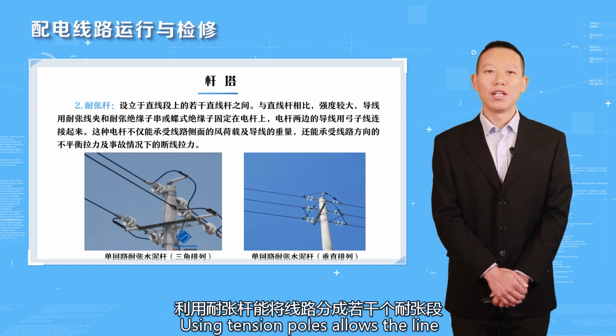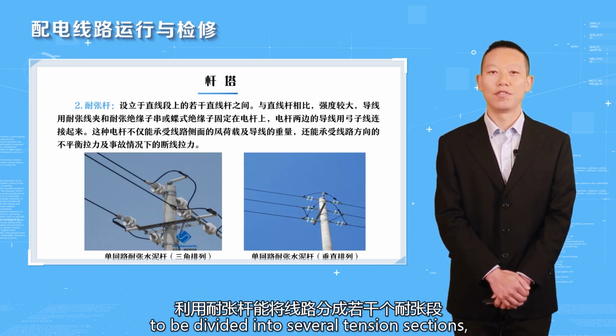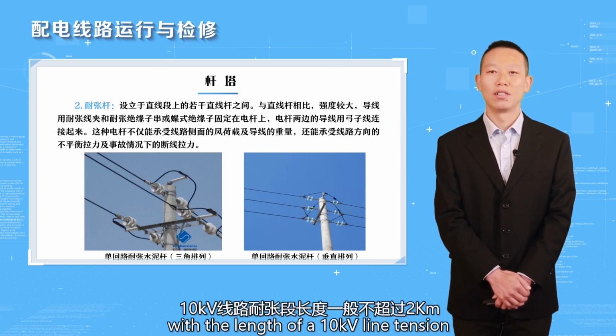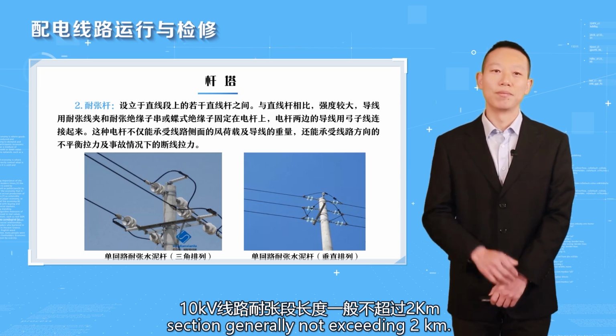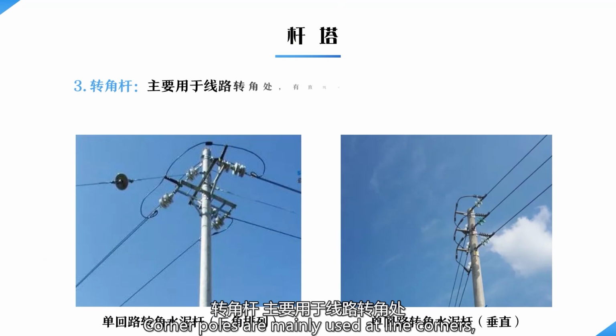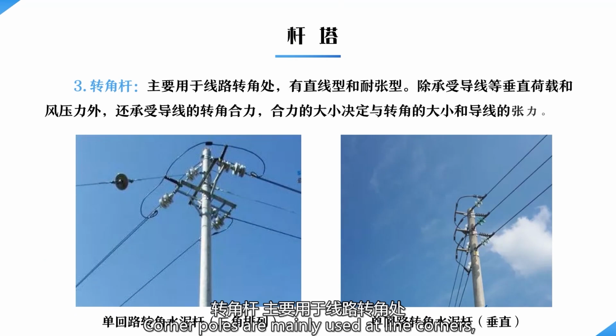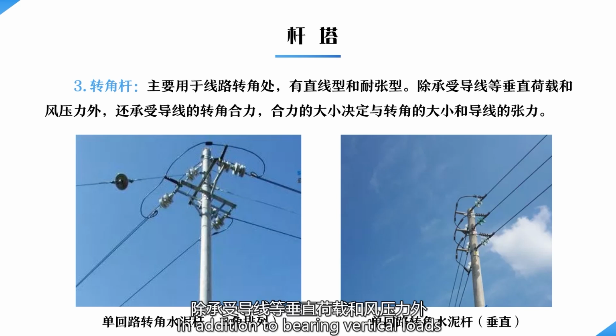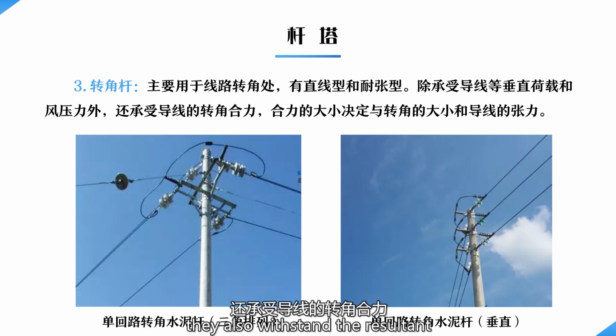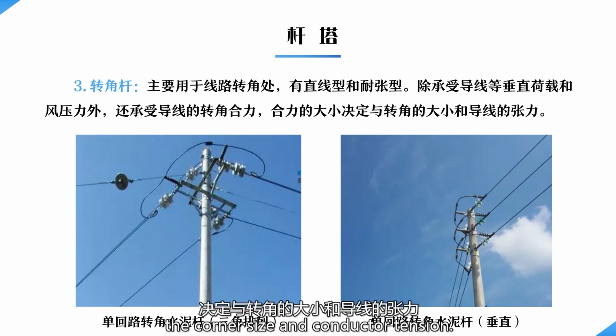Using tension poles allows the line to be divided into several tension sections, with the length of a 10 kV line tension section generally not exceeding 2 km. Corner poles are mainly used at line corners, and they come in straight and tension types. In addition to bearing vertical loads such as conductor weight and wind pressure, they also withstand the resultant force of the conductors at corners, which depends on the corner size and conductor tension.